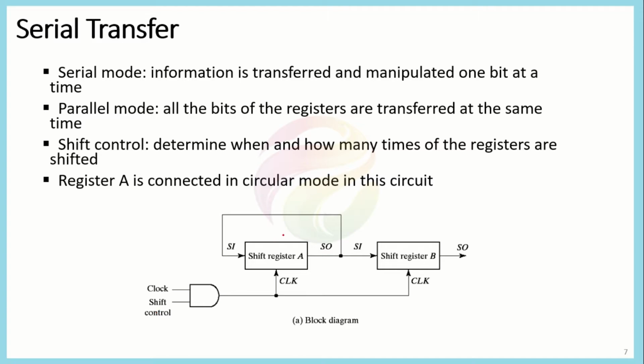There is another important thing present in this circuit. You can see that the output of the shift register is again fed back to the same register. This is done because we want to store the value of A. If we don't connect its output to the input, what would happen is that say A is a 3-bit system. It has a value of say 1, 0, 1.